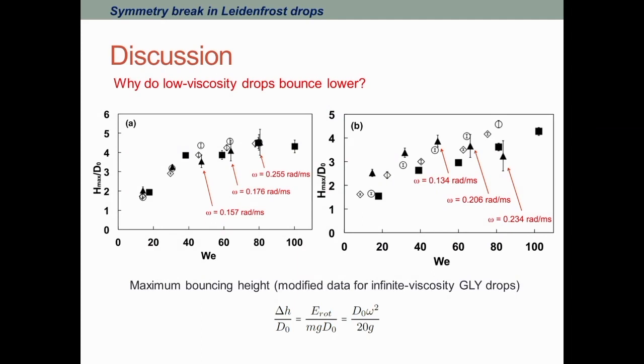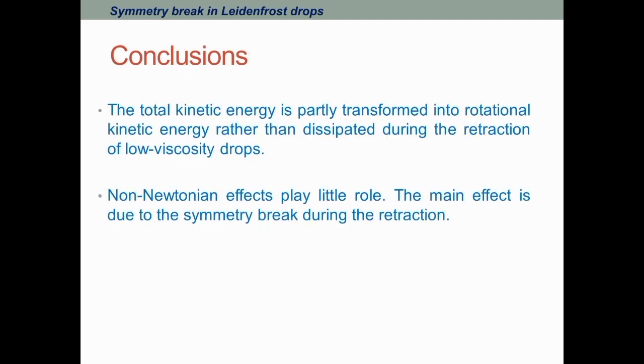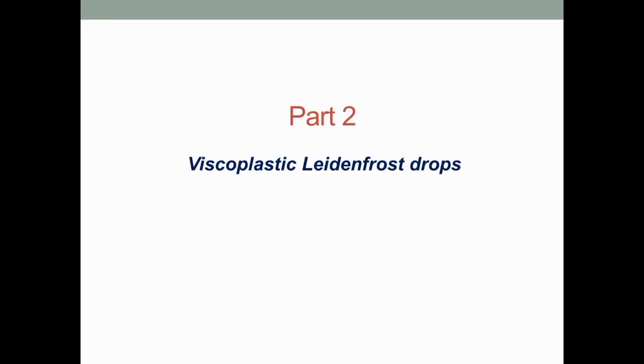You can see that all the data become almost consistent, which means that the total kinetic energy is only partially transformed into rotational kinetic energy rather than dissipated during the retraction phase of the low viscosity drops. Also, non-Newtonian effects play little role here, as you can see from the previous result. The main effect is due to the symmetry break during the retraction, which is observed only in the low viscosity drops.